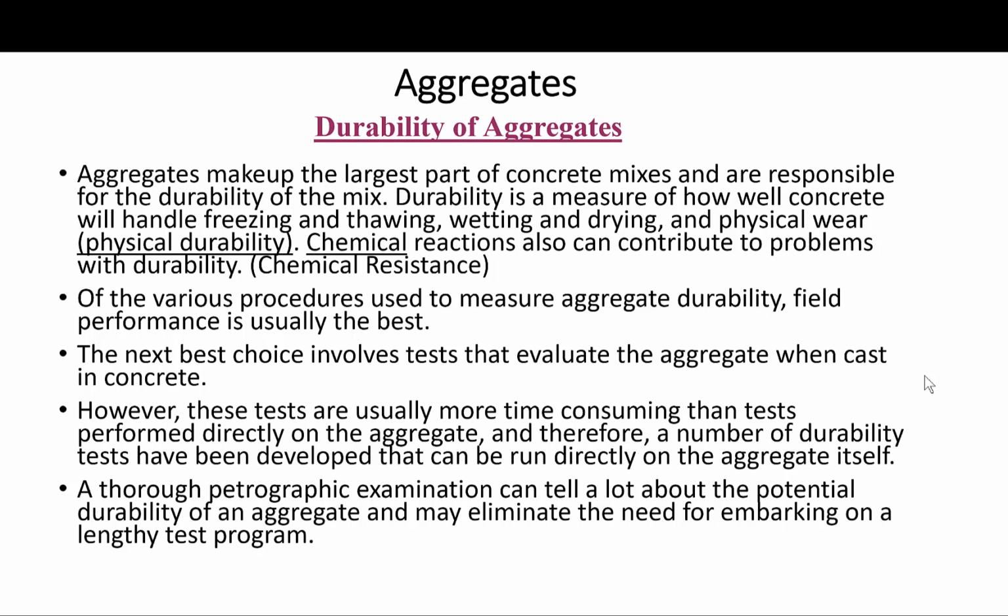It is important, in aggregate evaluation, that proper sampling practices be followed as laid down in ASTM C702 and D75. So we're talking about whatever testing program you're going to adopt. Most importantly, you need representative samples of whatever aggregates you're testing in order to make sure the tests are representative of your material source.